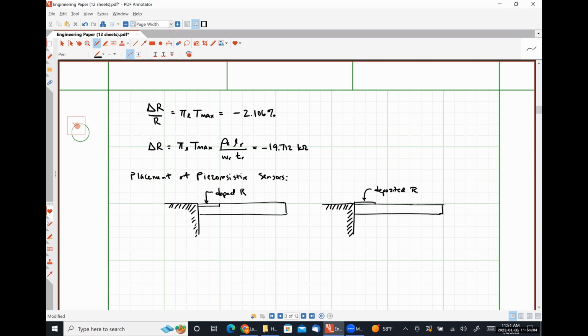So these are our two examples of effectively what we're going to consider good design choices, right? Where, for the reasons that we discussed previously, we are considering these good because they are thin with respect to the thickness of the beam and short with respect to the length of the beam, such that we're not having any cancellation of stresses, so we're not losing any sensitivity. And we can say roughly that our device undergoes a similar amount of stress, or similar amount of strain, across its entire length. Well, it matters.